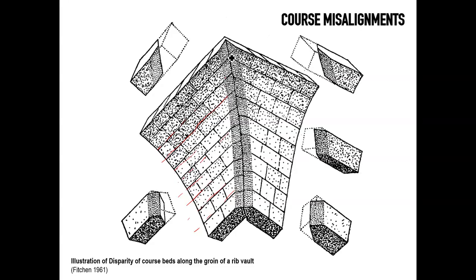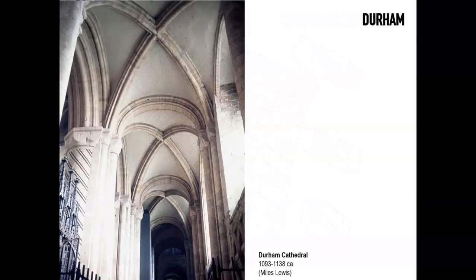And the rib, and then on the other side of the rib, you might have someone else, perhaps a different mason, working similarly, still in horizontal courses, but not necessarily having to worry about where everything would have to meet, provided that there's some coherence, of course, of the surfaces. And then the rib will come and cover all this. Now, the price to pay for this, as we said, would be to have a perfect stereometrical control of cutting stone, which was probably not available at the time.